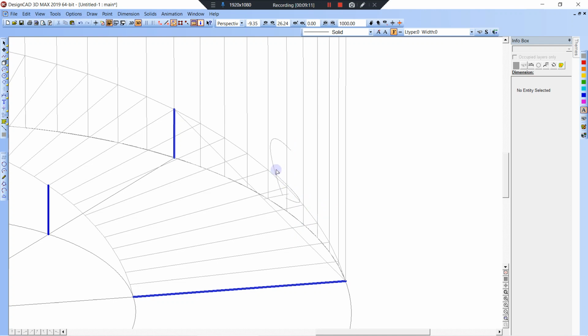I can't show it on the drawing, but you basically figure out 12 feet, measure, get a mark on the wall, come from the other side, mark 12 feet, get a mark on the wall, then just split the difference with your tape. Let's say it's 7 inches, you go 3.5 inches, that's the center. That's what we're looking for. And now you have your level, and you put it on that mark. Let's do this. I can't do that. It has to be V, Control K. I have to locate it.